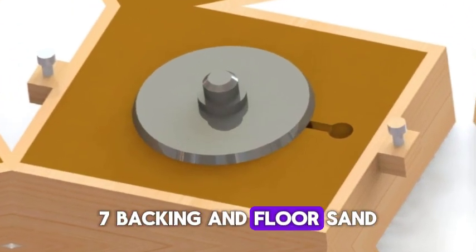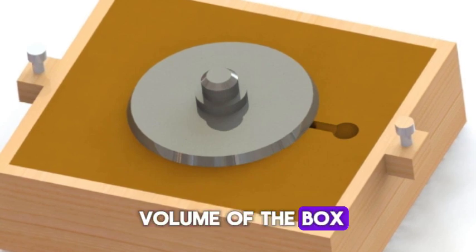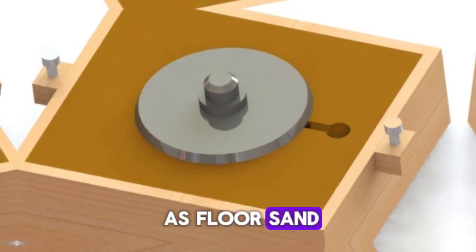7. Backing and floor sand. This casting sand is used to back up the facing sand and to fill the volume of the box. It is also known as floor sand.